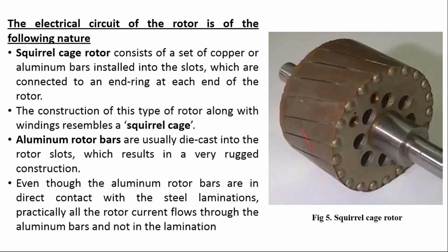So this is squirrel cage, and it is quite skewed. Basically, you can see the space for conductor bars. You can see it is skewed, and this is purposefully done to have the maximum interaction of the conductor bars with the magnetic flux, right? Have the maximum interaction, right?